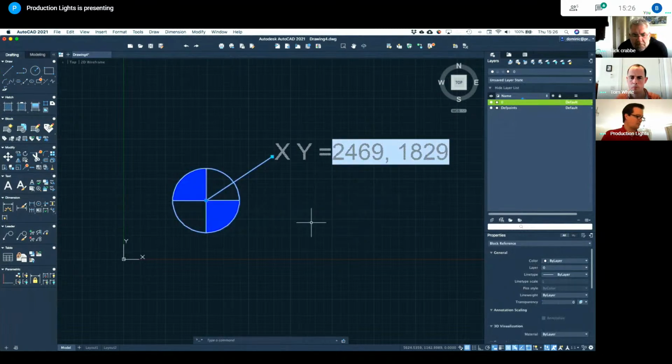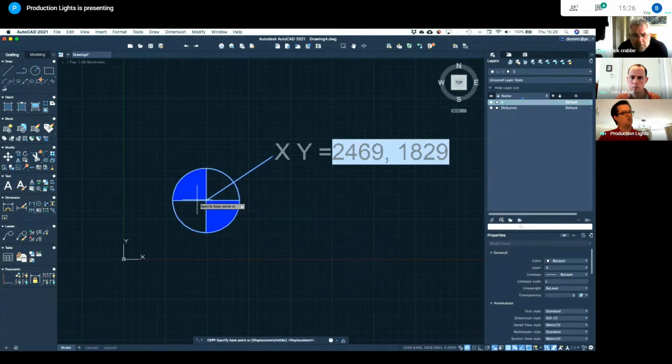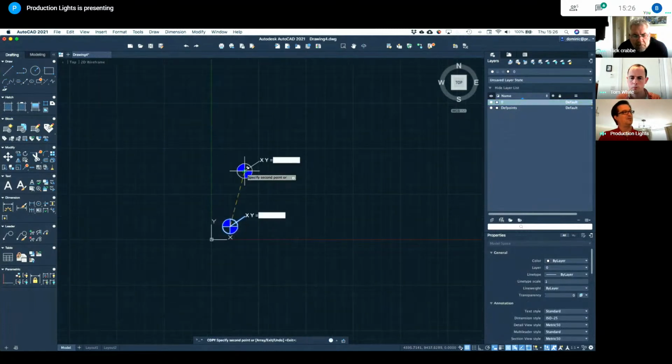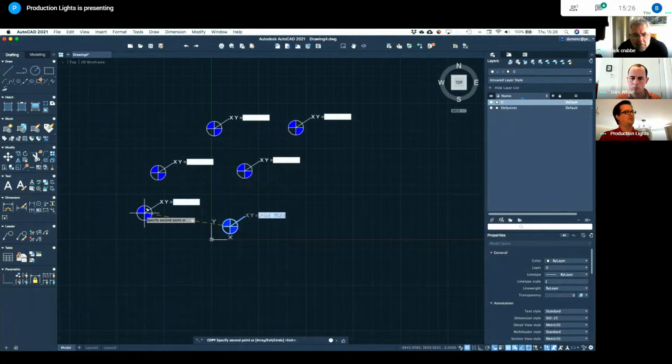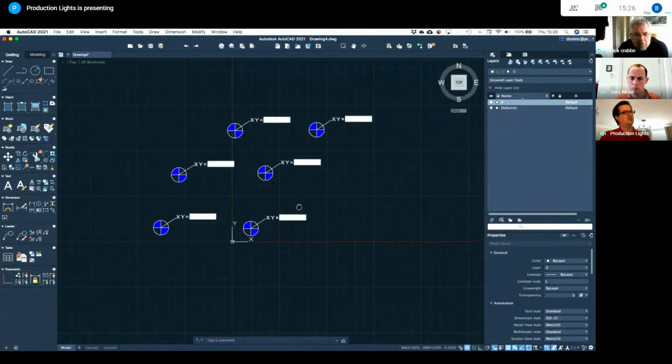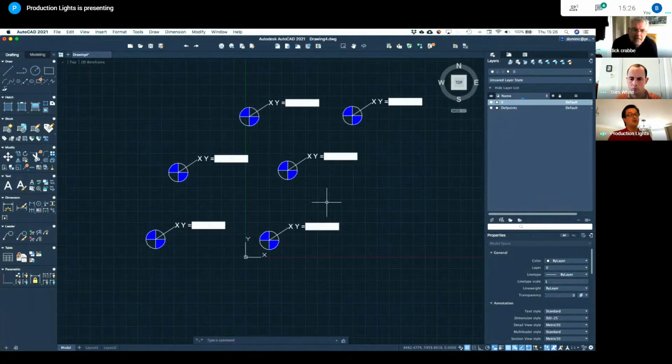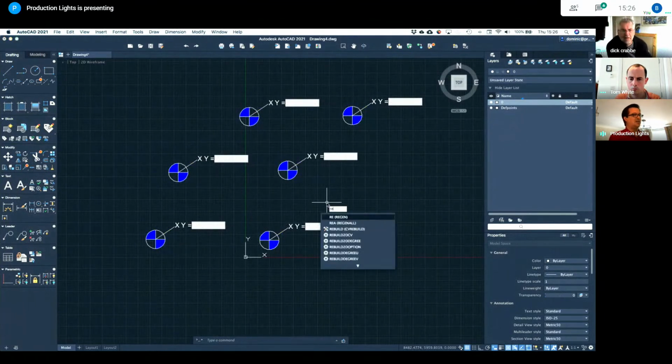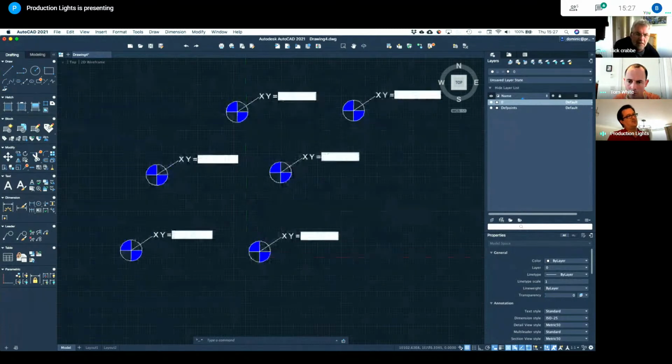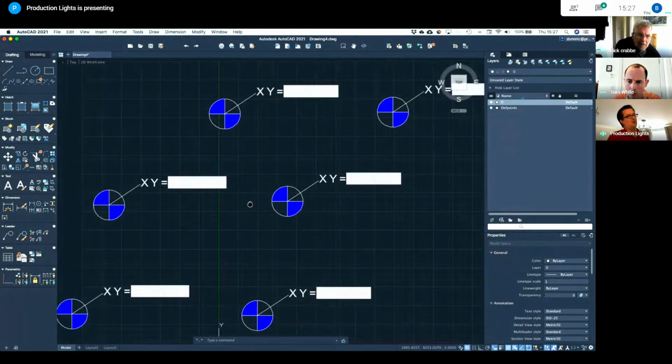And it would allow us, either in Tom's way, we could come along and add on a load of points. And there's a command that Tom's going to talk about later, but these are all the same at the moment. Hopefully the regen command will work, which is regenerate, regen. If I hit that, you'll see it's automatically updated all the XY information within those points. Can it do the Z as well?